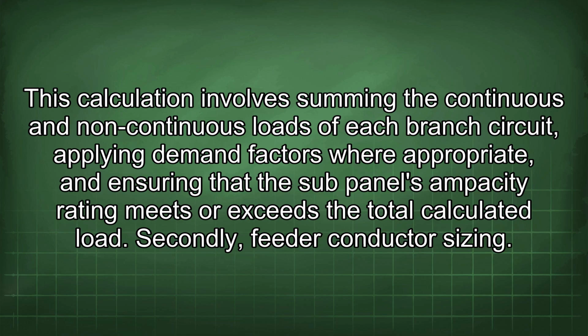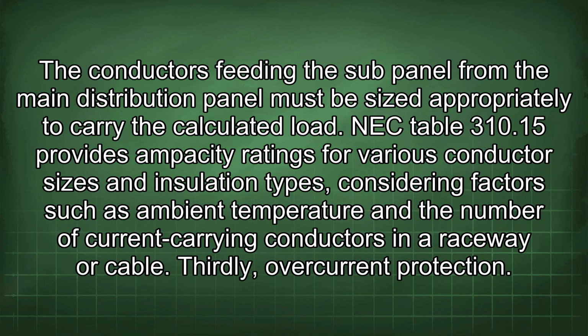Secondly, feeder conductor sizing. The conductors feeding the sub-panel from the main distribution panel must be sized appropriately to carry the calculated load. NEC Table 310.15 provides ampacity ratings for various conductor sizes and insulation types, considering factors such as ambient temperature and the number of current-carrying conductors in a raceway or cable.